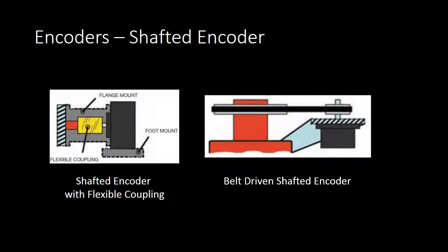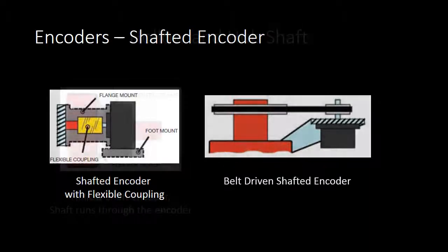These techniques also isolate the encoder from shock, vibration, and movement in the motor shaft and provide electrical isolation. This configuration is generally applied when a hollow or hub-shafted encoder is not available, when using a non-standard motor or the shaft movement is too extreme. The downside is that these techniques require more space and careful alignment, add more complexity, and can cost more.